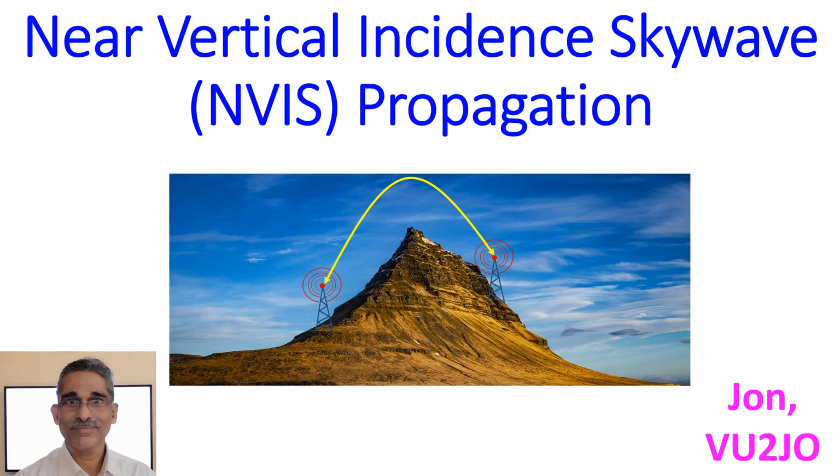At lower angles of radiation, the radio waves travel more distance through the lower layers of the ionosphere, increasing absorption and reducing the chance of refraction from the F layer with a good signal strength.